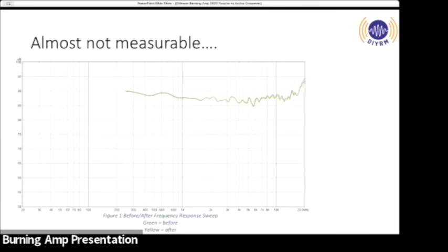If they are a power supply cap that has been under constant voltage at temperature in a cabinet that has gotten hot, then I have measured plenty that have died after 10, 20 years. But I see your point on stability. It's super long term, aging type stability. There is some of that, but a film cap or an inductor, no, they're not aging. Yeah. What about the tolerance issue on the electrolytics? Well, you can't get, that I know of, plus or minus 5%.